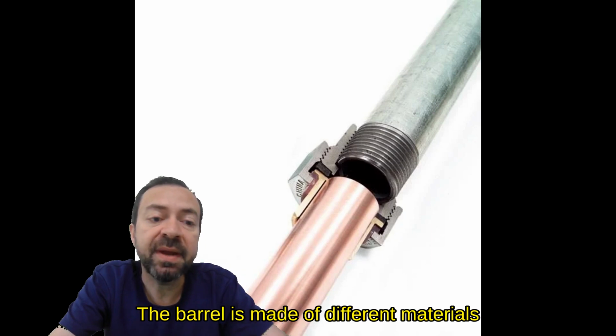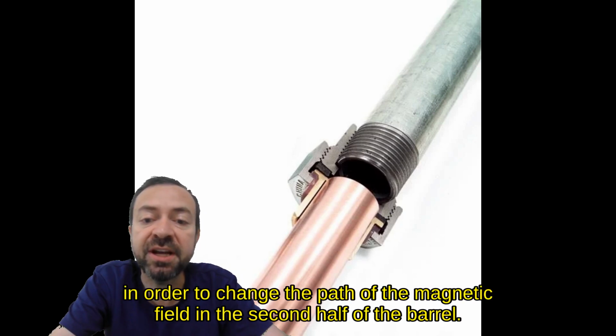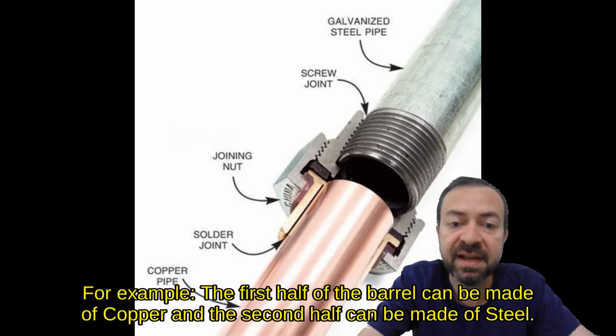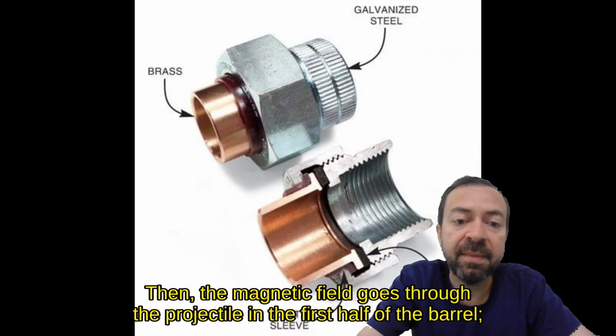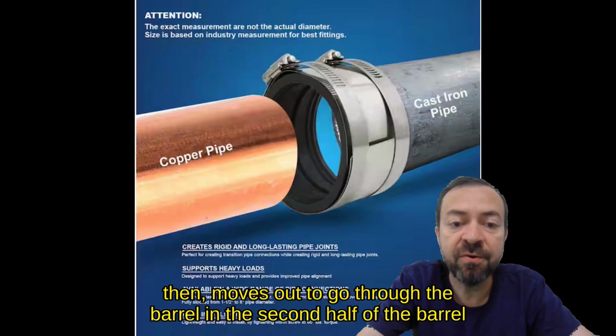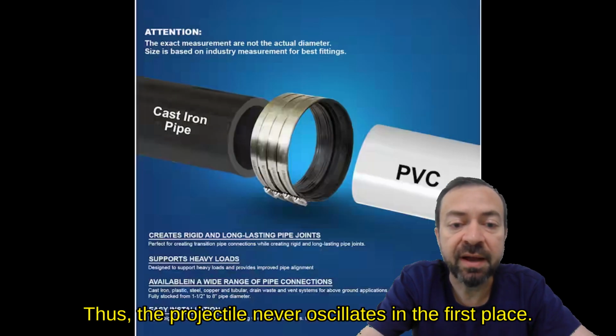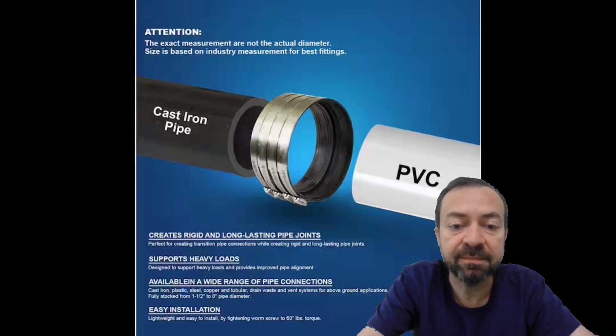The barrel is made of different materials in order to change the path of the magnetic field in the second half of the barrel. For example, the first half of the barrel can be made of copper and the second half can be made of steel. Then the magnetic field goes through the projectile in the first half of the barrel, then moves out to go through the barrel in the second half of the barrel because the barrel is closer to the coil. Thus, the projectile never oscillates in the first place.